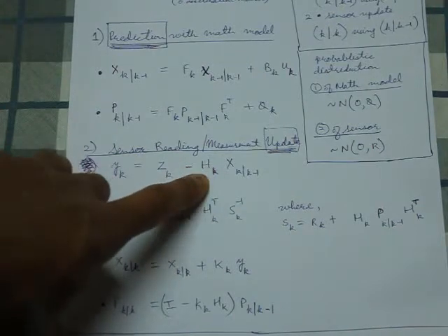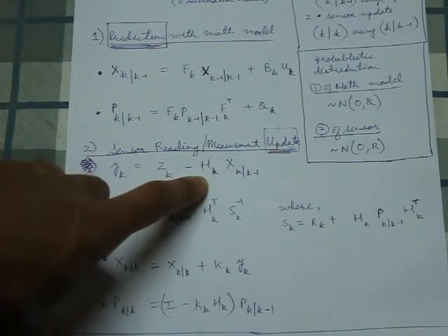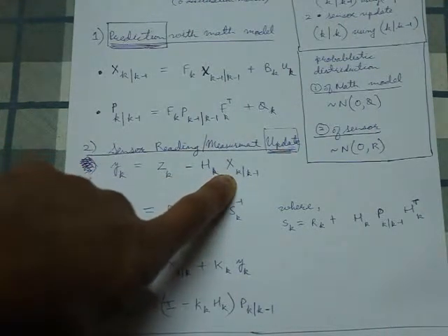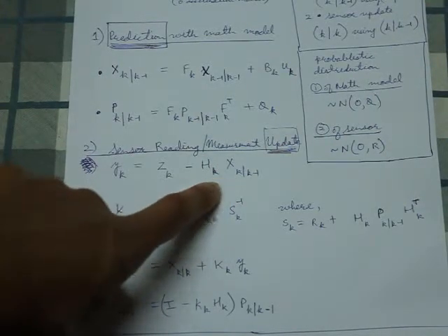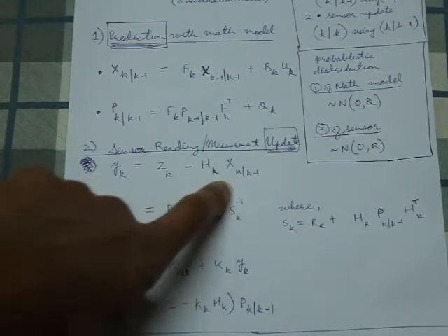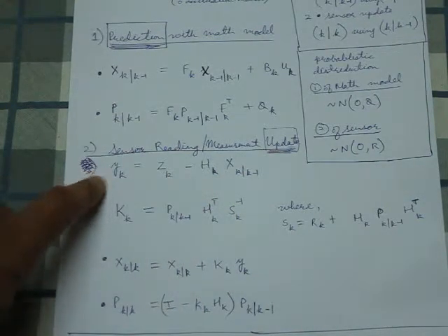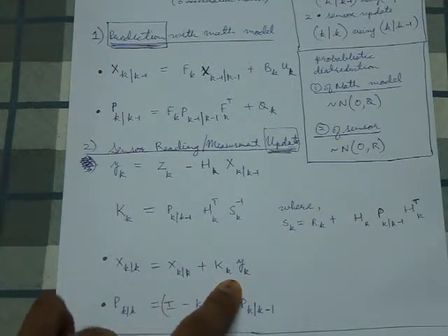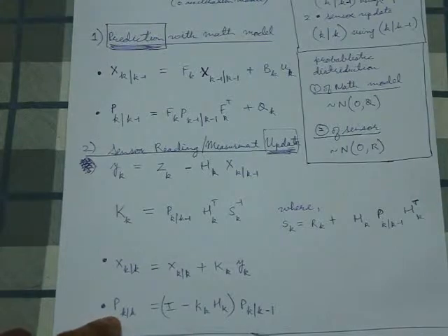So now we know what H is, we know how to use this measurement function to translate the entire state matrix into only the position value so that we can find the difference between the actual position and the estimated position. This gives us the error. This error is later used to update the state vector and the corresponding probability distribution.